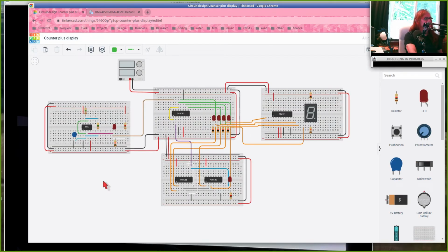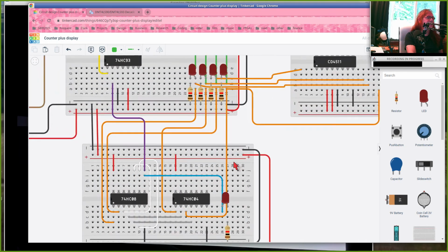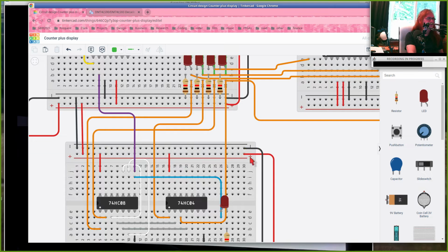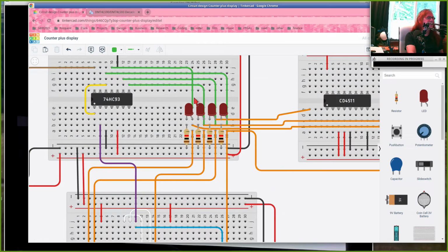All right. So the other comment on Tinkercad, I'm going to require that when you do circuits on Tinkercad for Lab 6, that you treat these like physical protoboards, which means maximum of 1 wire per hole, right? So if I wanted to do something with this signal right here, I can put this signal into this hole up here. I can pull it off of the LED in this hole. I can feed it into my decoder in this hole, and I can run it into my reset circuit from this hole, right? Instead of shoving all 4 wires into one hole.